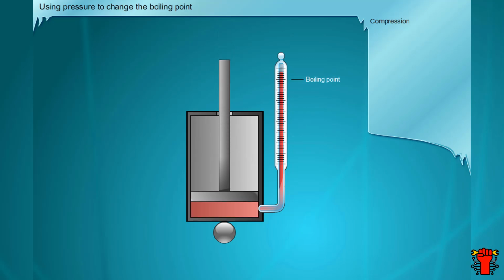The gas is compressed, causing it to become very hot. But something else is happening too. The boiling point is shifting upward. Due to the difference in temperature in the surrounding area, which is the sphere in this case, the gas is now releasing heat and will soon start to condense. The temperature remains constant at boiling point until the latent heat of condensation dissipates. Only at that point is the gas completely liquefied. It can then continue to cool down.